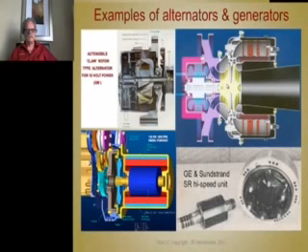Intake air comes in here, and then it passes over into this chamber, which has ignition and fuel, and so that high pressure air combusts with the fuel and causes a very high pressure, and that drives this turbine, and there's the exhaust. So the compressor turbine is connected to the combustion turbine.